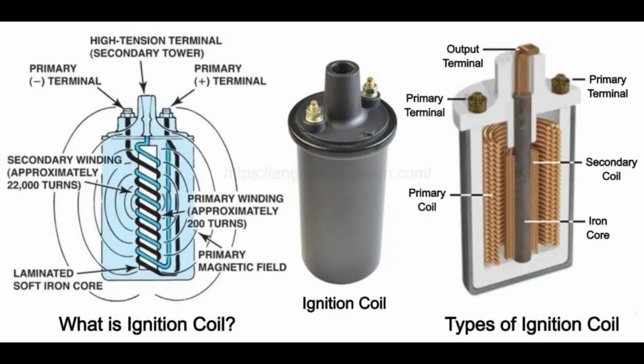The high voltage wires that run from the ignition coil to the distributor, and then through the distributor to each of the spark plugs, are called spark plug wires. Mechanical contact breaker points and a condenser are required in every such ignition system. Today, a power transistor is used by an electronic ignition system to provide pulses to the ignition coil. A diesel engine depends on compression to ignite the fuel, so the air mixture does not need an ignition system.